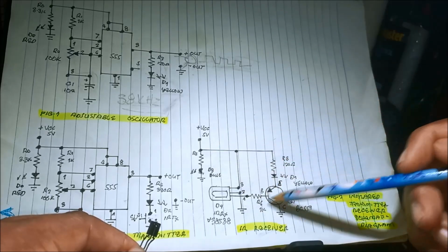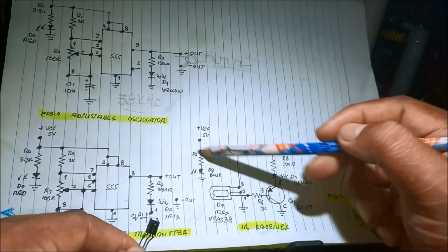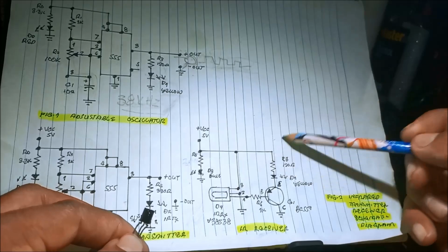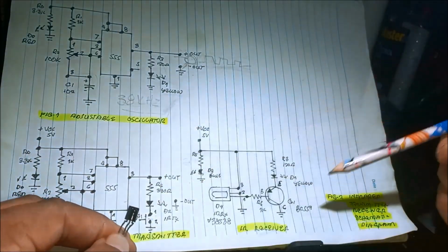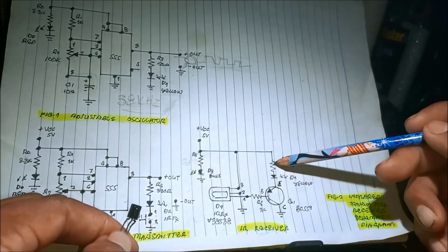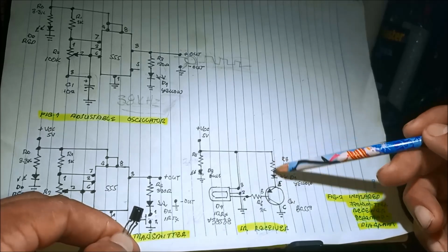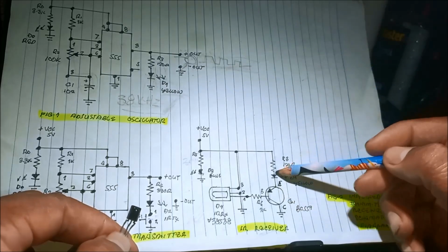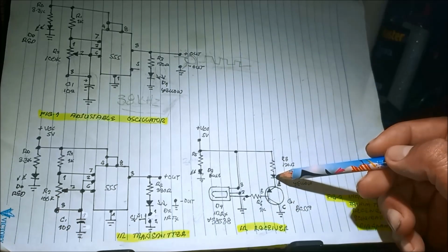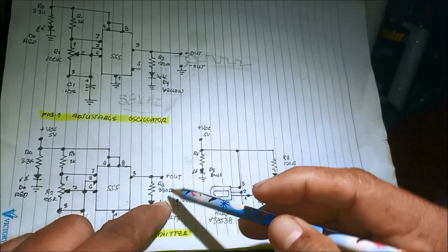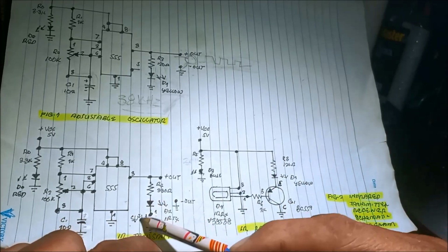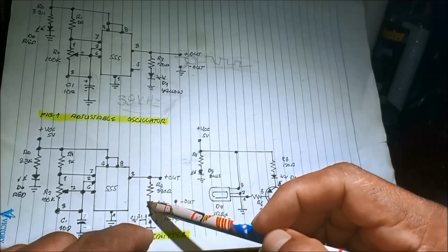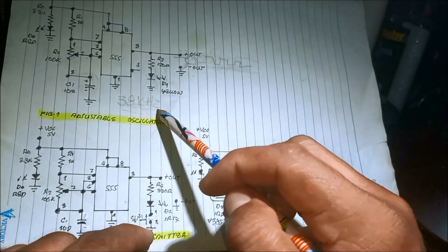What happens now to the circuit? In this new circuit, we have the power LED. I think this is 3.3K, same. And then same as the transmitter, power LED, and then the output LED, yellow, the same output we used in the previous oscillator. So when we transmit using the push button, it will modulate a signal of 38 kilohertz.